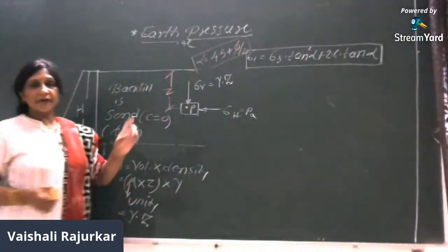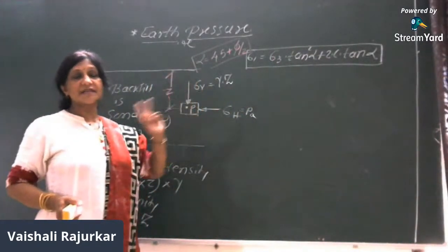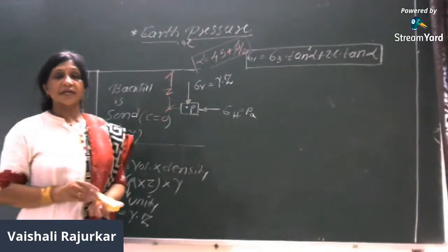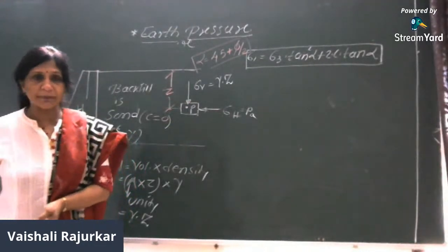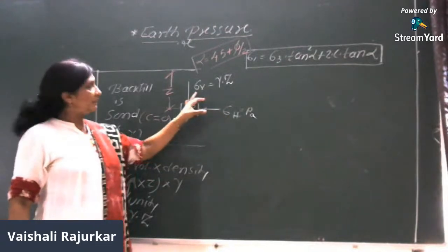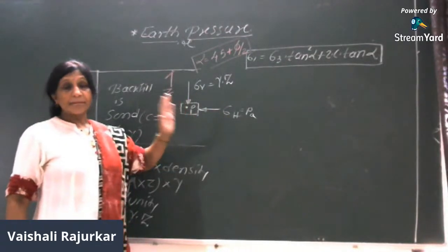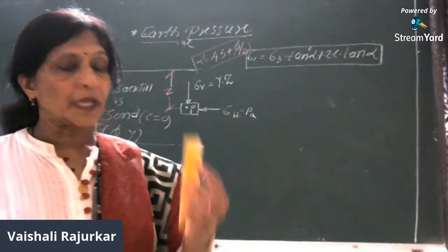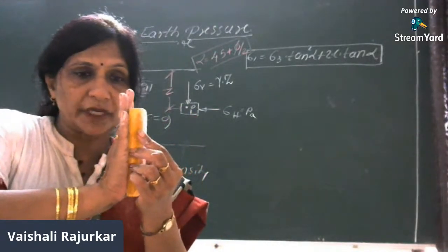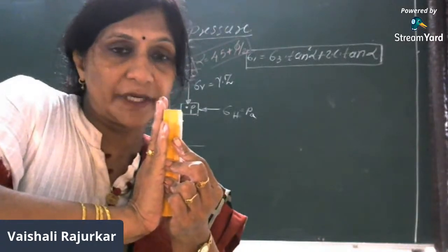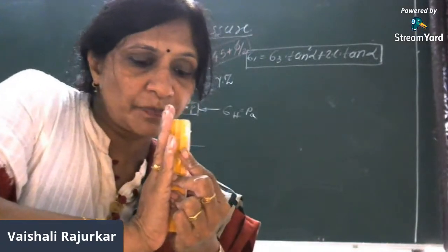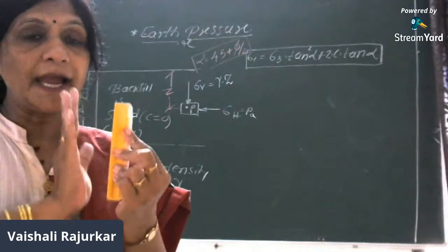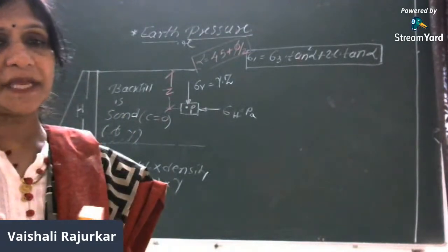Now in this case, sigma 1 is major principal stress, sigma 3 is minor principal stress. Now tell me, out of these two, which will be assumed as major and which as minor? At this moment, we don't know. But here we have assumed that this is the case of active earth pressure. Suppose I am applying the pressure over here on this soil mass. The pressure will be maximum. Once the wall moves, there is a release of the pressure.